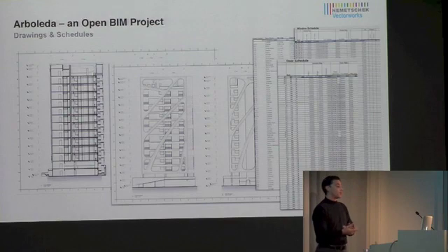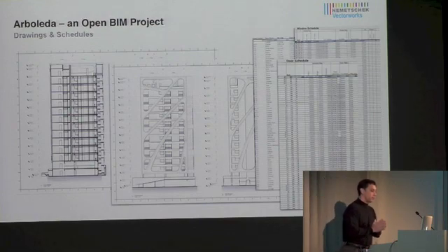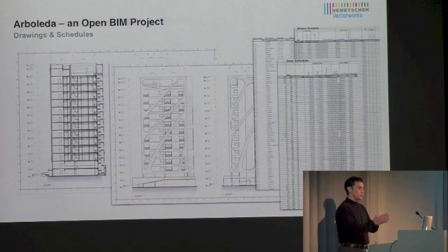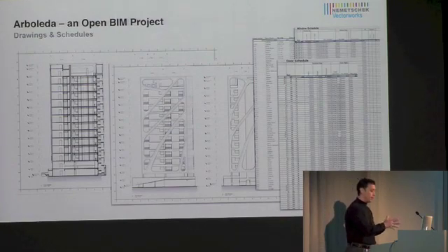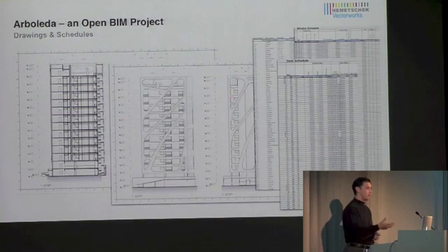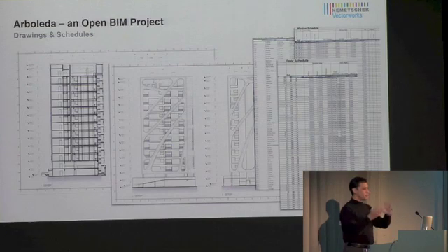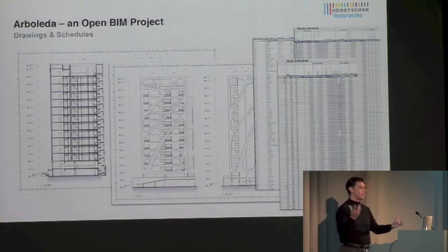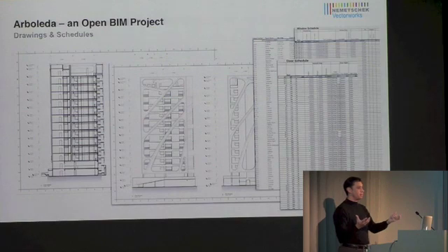And about construction documents, you understand that inside Vectorworks, you are fully capable, if you are really using 3D and creating a BIM model inside the program. You get the model, of course, and out of that you get your elevations, your sections, your floor plans. But Vectorworks contains a spreadsheet, and if you modeled it, if you drew it, then the spreadsheet knows what is happening inside the 3D model. So I was able to count the doors, count the windows, maybe put a price to that.